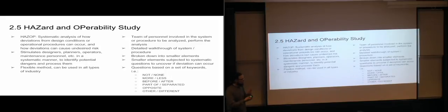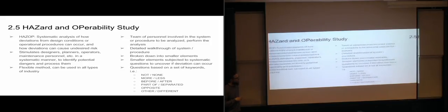These are keywords that you use to come up with questions. So you try to come up with questions with regards to more or less. What if we put more load on this lifting equipment? Putting less load on lifting equipment is not going to cause any unwanted risk. But if you put more load on it, you could overload it, and that's going to create risk. So that's one of the ways of using these keywords.